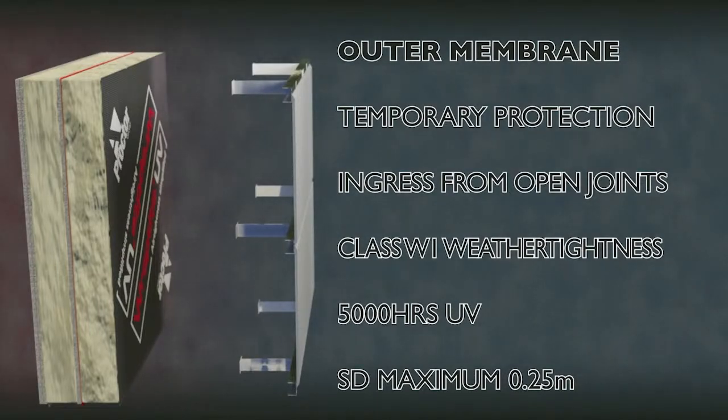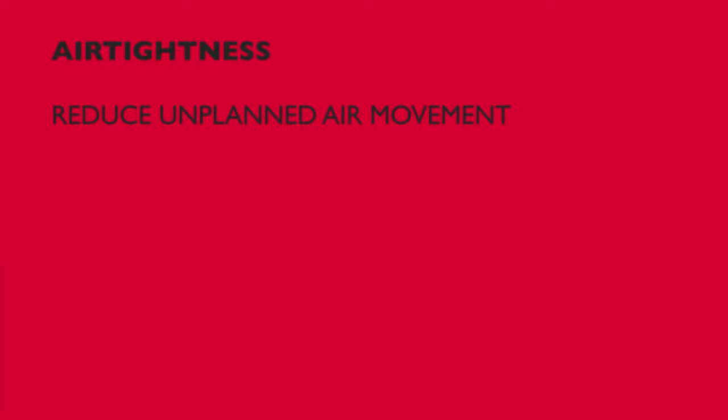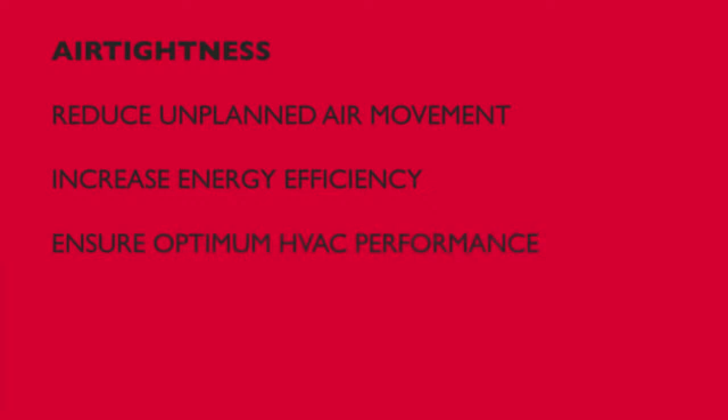control, and fire performance. Good air tightness, or reducing planned air movement through the building envelope, is an important component of the overall energy performance of structures. As the levels of fabric insulation in buildings increase and HVAC and heat recovery systems become more efficient, minimizing air leakage is critical to ensure everything else works optimally. All the energy assessment methods in common use, such as SAP, SBEM, and the Passive House Planning Package, all holistically consider the effects of air tightness and insulation on overall heat loss.